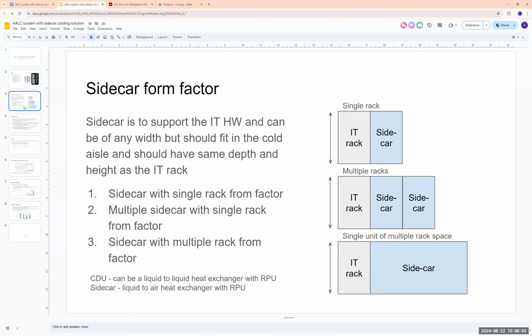Yeah, the problem is not the power per chip. If it is 2 kilowatts, but the surface of this chip is 2 times a 1 kilowatt chip, it is the same. Otherwise you have a problem with the power density, power per square centimeter. If you increase the power per chip and increase the size, you can go with the same technology, the same cold plates, but bigger.